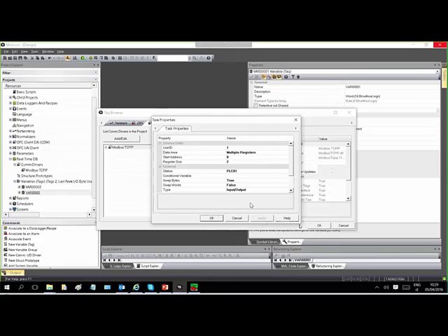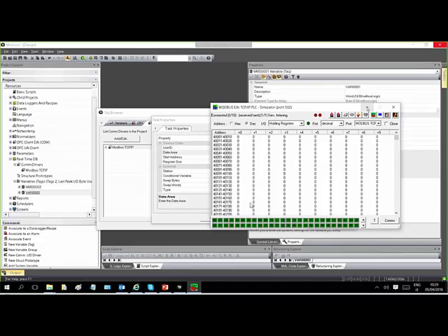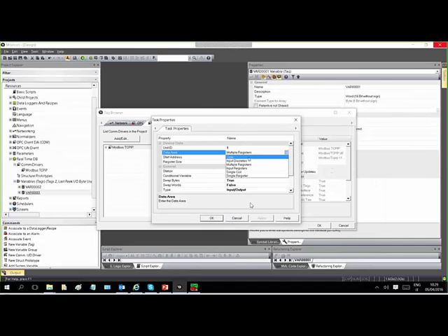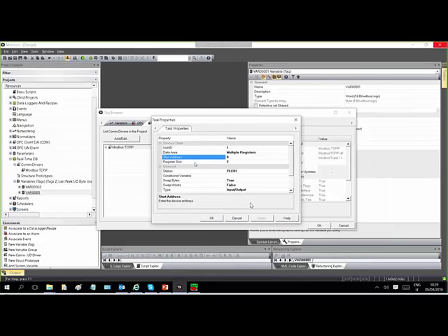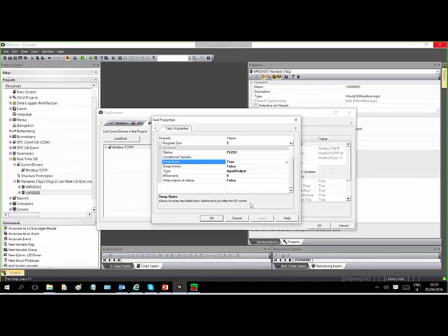And here I have the task properties. So I will share this variable that is a data area multiple register, holding register in Modbus, or depending on the driver: coil, input discrete, multiple register. Starting address, 0. Size of the register. Station will be PLC1, the only station I define. No conditional variable, no swap in this case.